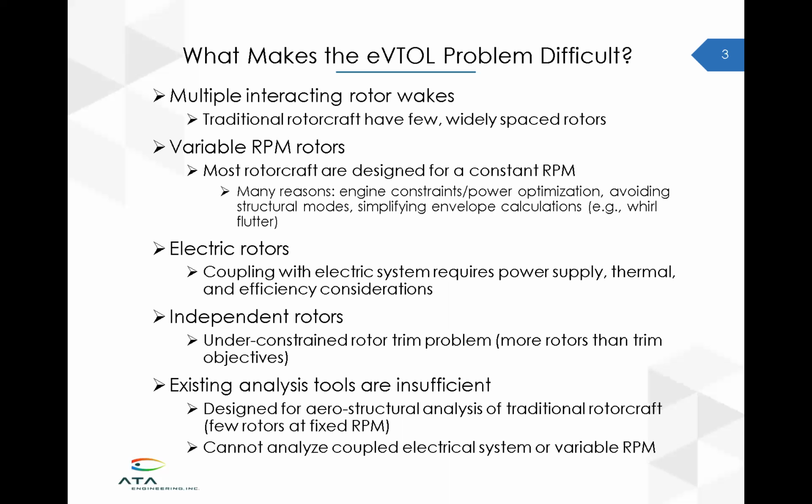The independent rotors introduce a different trim problem that is under-constrained because you tend to have more rotors than degrees of freedom that you're trying to control. And one of the reasons that we're developing this Modelica library is because we found that a lot of existing analysis tools for rotorcraft are insufficient. These are usually designed for rotorcraft with a fixed RPM and very few rotors.